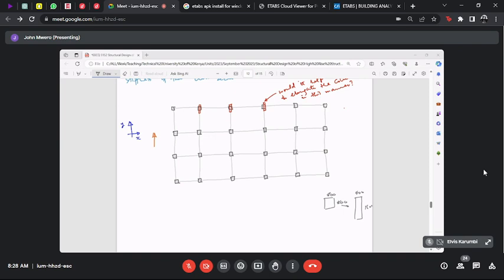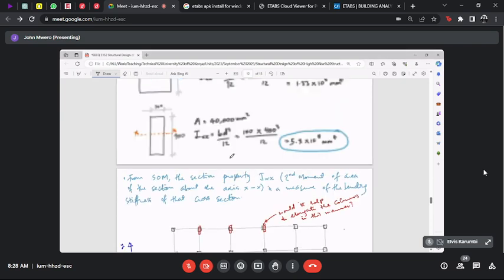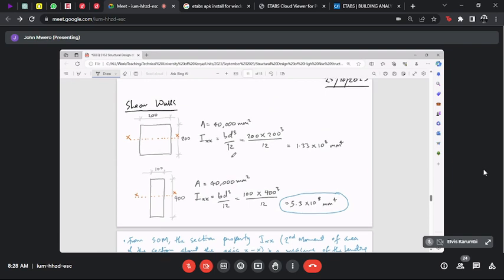Yes, I think it will help because the stiffness will increase in that direction, and the columns will not bend that easily. Correct. So what Elijah is telling us is basically what these numbers are telling us. That just by rearranging the element to have a bias in stiffness in the direction where we need the stiffness, it can actually help to stiffen the building significantly.